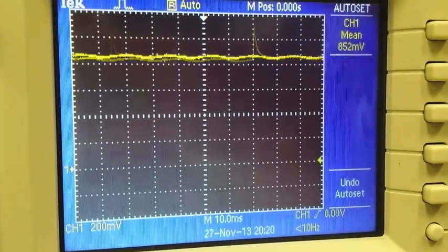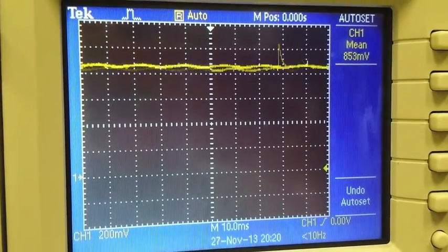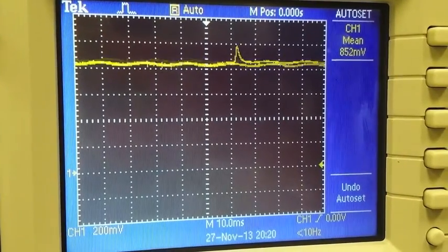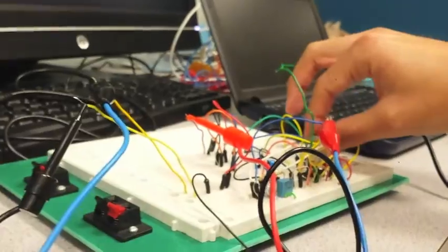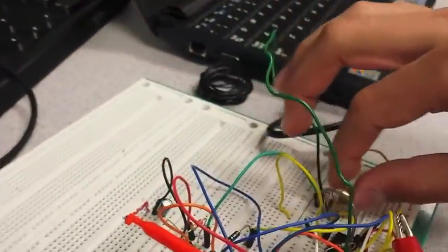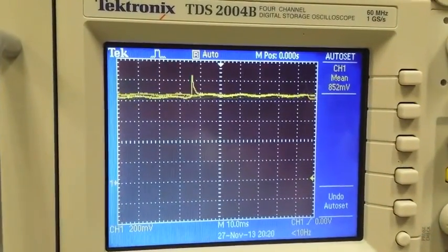In our demonstration, the transducer consists of a piezoelectric plastic film that responds to the tremor motion of the hand of the subject. Then the input amplifier creates a high-pass frequency response based on the capacitance of the sensor combined with the amplifier's input resistance.